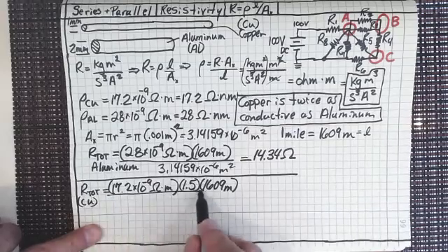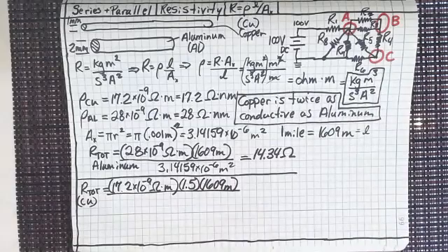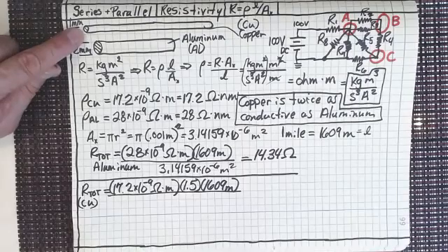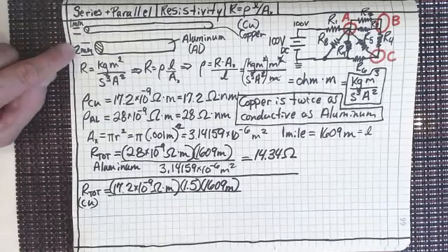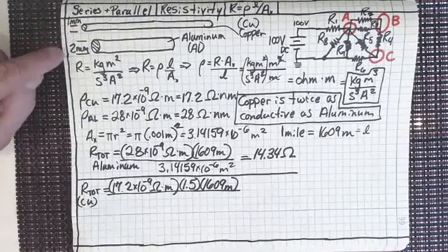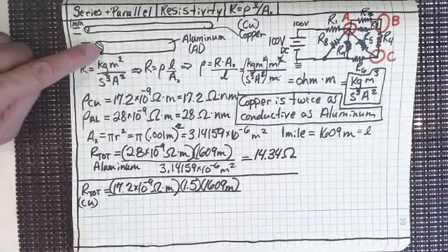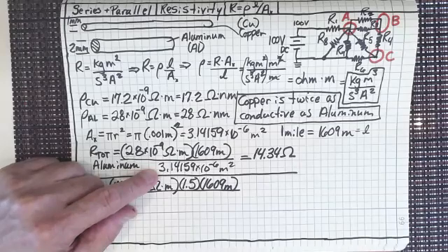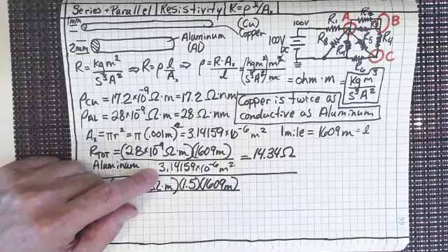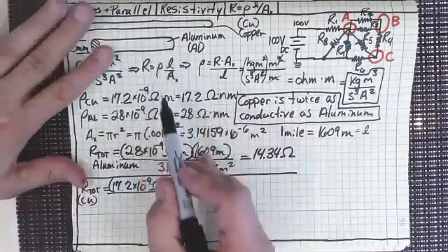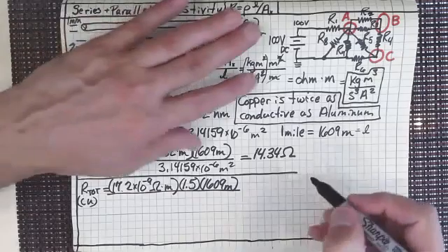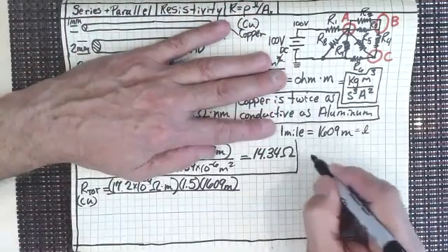Now, that cross-sectional area is going to be much, much smaller, isn't it? Because the cross-sectional area goes down by the square of the radius, doesn't it? So 2 squared is 4, 1 squared is 1. So I would think that it'd be 1/4 of the cross-sectional area that I had here, 1/4 of 3.14 times 10 to the minus 6. So I'm thinking it's going to be something that's more like 0.8. And everybody should do this, right? You sort of think about this, and then if you put it in your calculator and it says 6 billion, you know your calculator's wrong.